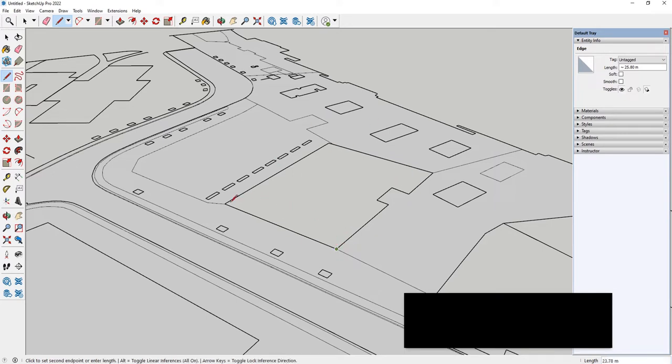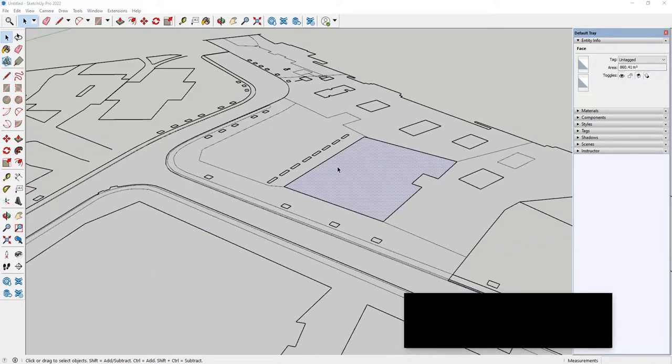Let's left click. And I'm just going to move around to all of these points that we imported from the CAD. And these are all going to be useful to us because as I complete this shape that we're defining, it will ultimately produce a face. Now, if I select the space around it, that's all in that landscape group. But if I select this face, this is now a completely separate entity. And just for the sake of organization and moving buildings around, as I know that's a component of Project 2, at least for the studio portion of it, that'll be really useful to us. So we've got our building footprint and our landscape in separate layers. Perfect, that's exactly what we want.